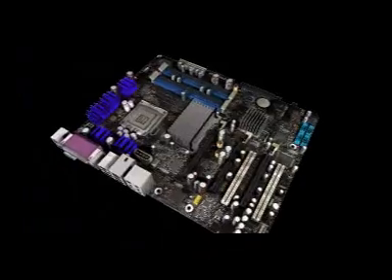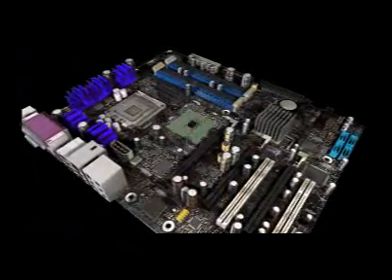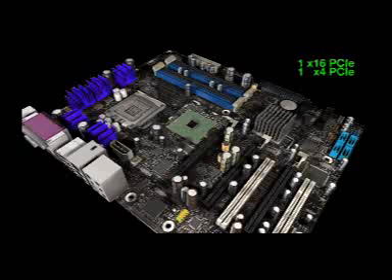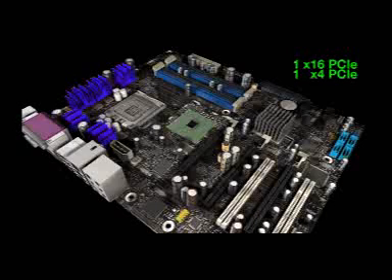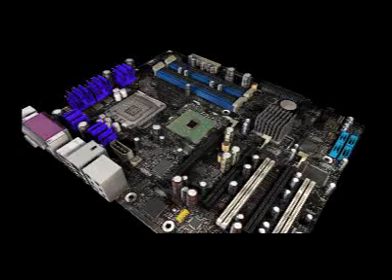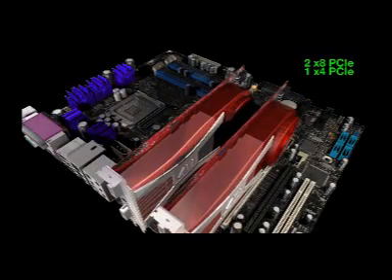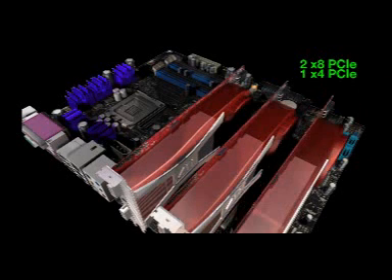The Intel 975X Express chipset delivers CrossFire support through 16 lanes of PCI Express connectivity stemming from its memory controller, and 4 branching off the ICH7 hub. On a fully featured motherboard like Intel's famous Bad Axe, 2 CrossFire cards consume 8 lanes each in the 2 primary graphics slots, while a third slot is available for upcoming ATI Radeon graphics physics processing. Enthusiasts eyeing additional flexibility and performance can opt for the CrossFire Express 3200 platform from AMD, sporting a total of 40 PCI Express lanes from a single piece of silicon.